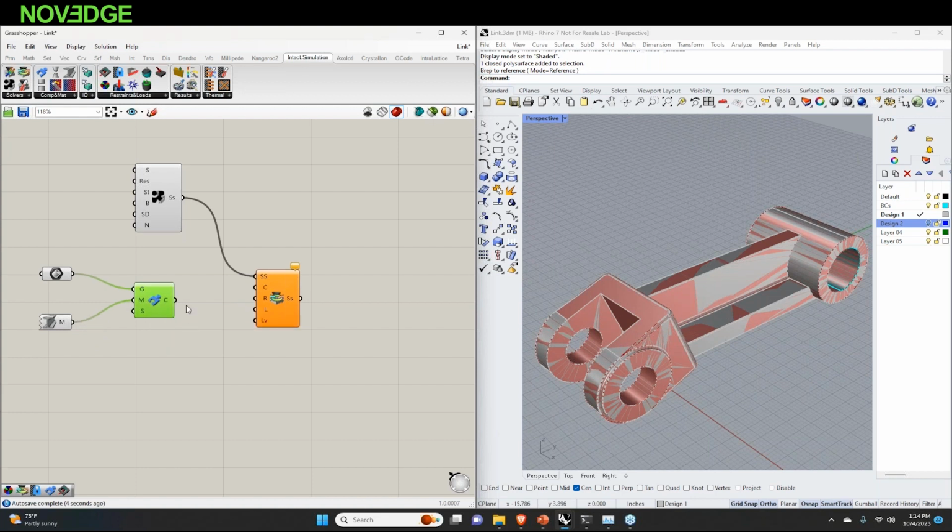been fully specified. I plug that into the components input on the stress solver, and we see that it's turned red. And looking at the help button, we see that we need to specify loads, and we need to specify restraints or displacement boundary conditions. So we'll start with specifying restraints.